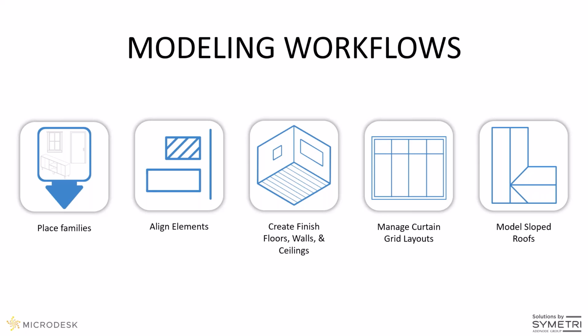We looked at managing our curtain wall layouts by adjusting the spacing of the curtain grids easily with the curtain grid designer. And lastly, we looked at how to use Naviate's roof features to add slopes to our roofs using those Naviate annotation elements.